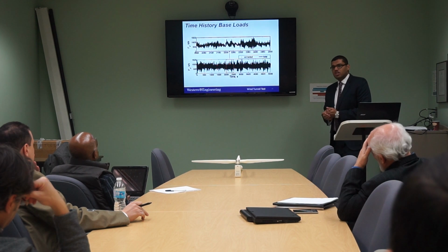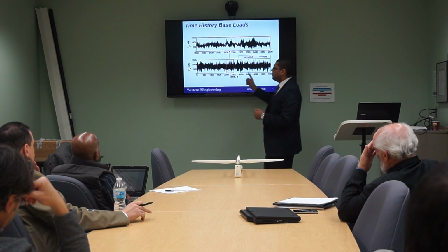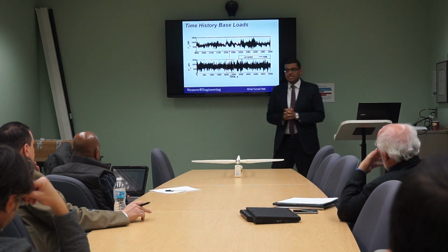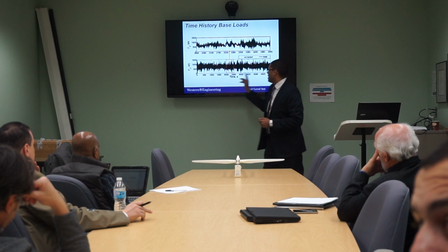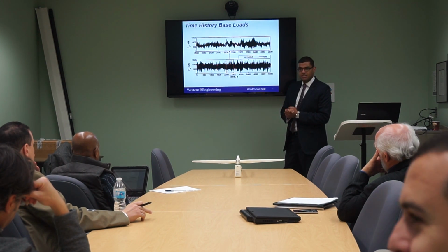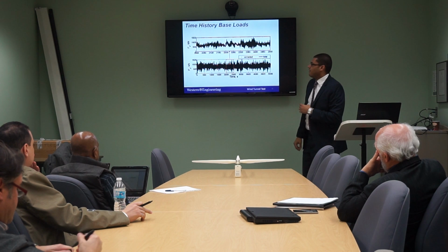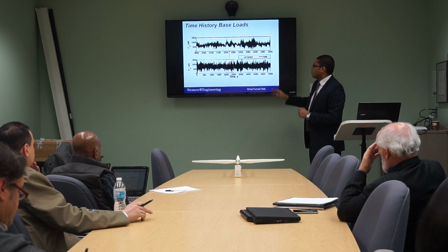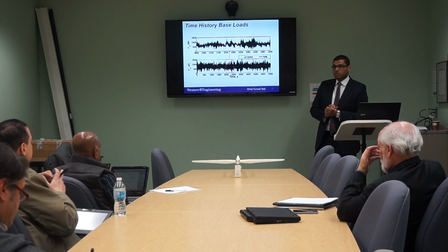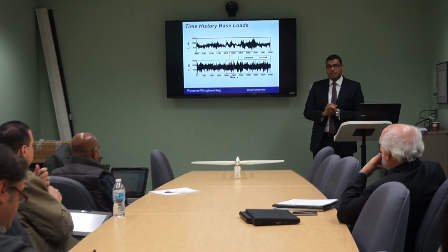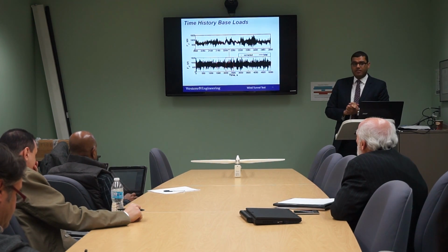After we have finished our wind tunnel test with different angles of attack, we will be able to get the time history as 6 components at the base of the wind turbine. We can see here, this is Fx, and this is the time between 0 and 5,000 seconds. This is scaled up between 2,000 seconds and 2,500 seconds. So we'll be able to get the actual time history for the 6 components at the base of the wind turbine. We tested the wind turbine at the parked position. The actual wind will be relative to 47 meters per second.